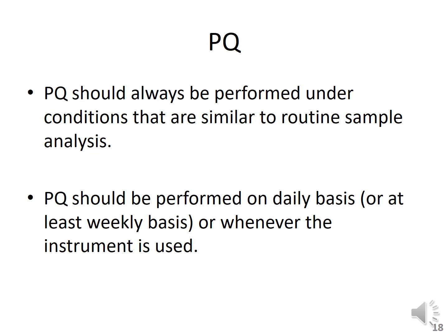right? Performance qualification should be performed on a daily basis or at least weekly basis, or whenever the instrument is used. If the instrument is not in use on a daily or weekly basis, whenever you are using the instrument, you have to do the performance qualification, and you have to keep the record of it, and it will help you in maintaining the instrument for a longer time. Okay.